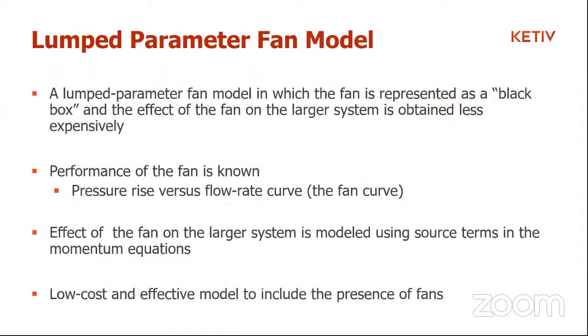The other thing is using a lumped parameter fan model. In the lumped parameter fan model, you are basically specifying a boundary condition at one particular fan plane within a fan zone. And it's almost like specifying a pressure restriction curve, similar to what we did for the porous media case.